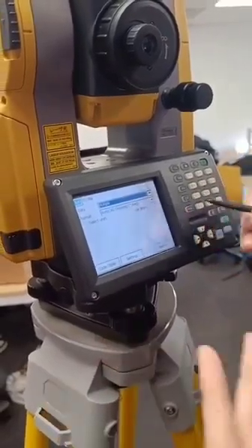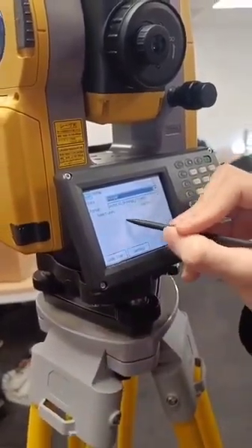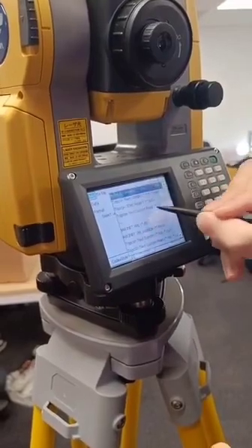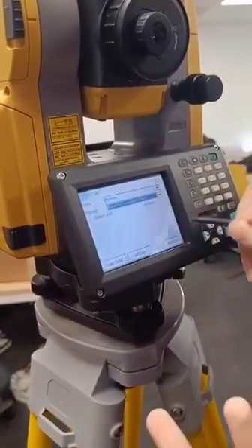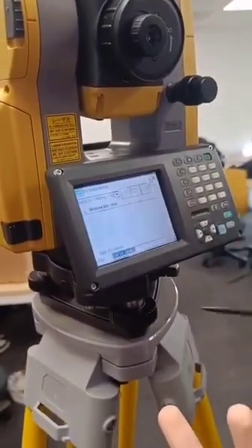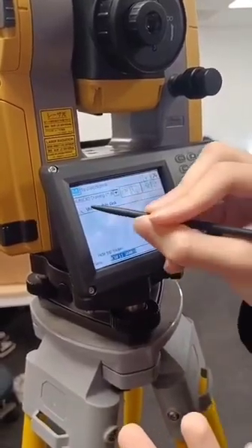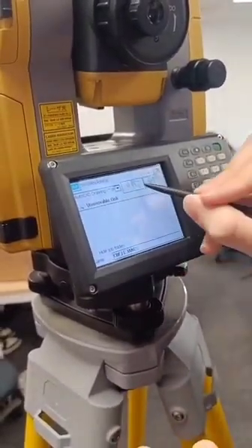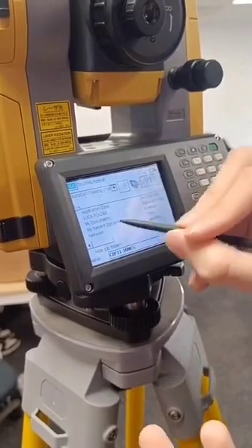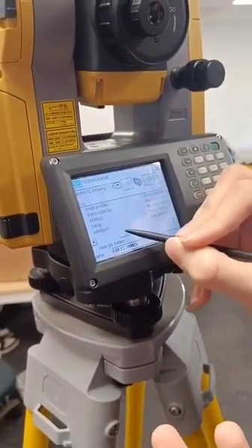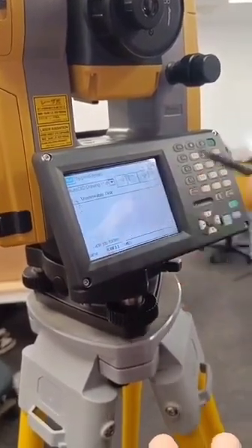There are 2 different formats you need to export as. The first one in here is AutoCAD. The default could be whatever was there last time. So just AutoCAD, next. It should be in removable disk here already. If it's not, you press this button to head to the root folder, and then just find removable disk. That's where you go.